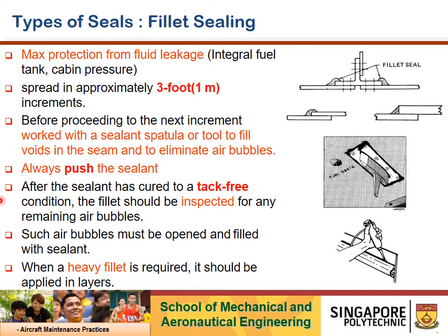Alright. So the rest will be air bubbles must be filled with additional sealant, and when a heavy fillet is required, it should be applied in layers. Alright, so that means you should apply multiple layers of fillet.